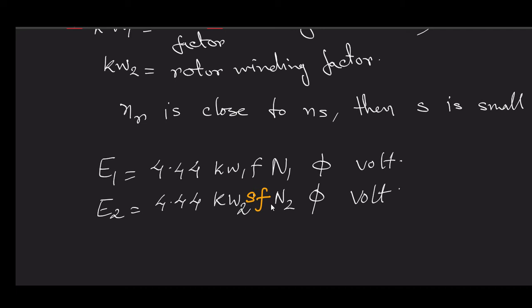Even if the higher order harmonics have frequency integral multiples of the fundamental, if the fundamental itself is 15 Hz, then 5 times that will be 75 Hz. But the fifth harmonic for the stator will have a frequency of 250 Hz, while this one has 75 Hz.